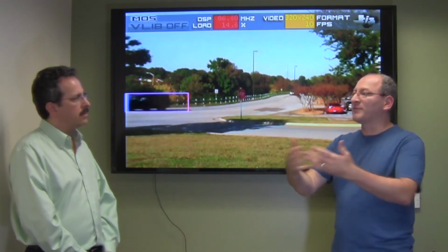So part of that is really looking at your variables. Are they in the right type? Fixed point, floating point. And after that, taking a careful look at the flow of your algorithm, of your solution. You don't want to be pushing in and out of the memory entire images, entire frames. That's something people are learning with some pain, actually, when they try to go from OpenCV to embedded. So it's really important to be fully aware of the big picture before you step in and declare, this is the code I want to really run on my product.